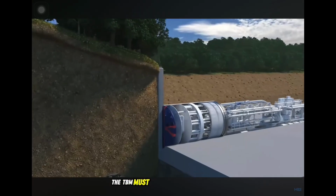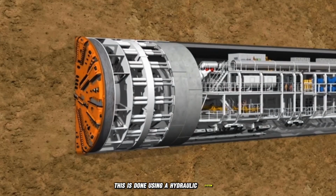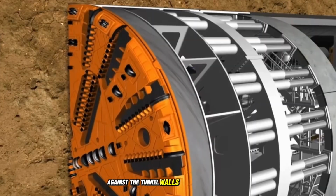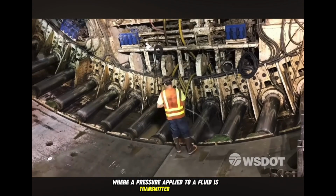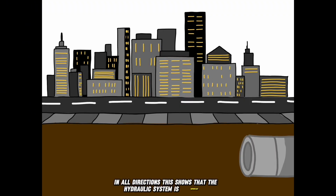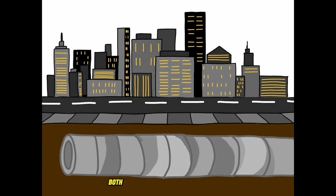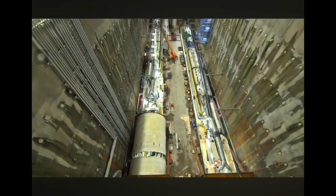The TBM must also move forward while cutting. This is done using a hydraulic system. High-pressure fluid is pumped into thrust cylinders that push the machine forward against the tunnel walls. This uses Pascal's principle, where pressure applied to a fluid is transmitted equally in all directions. This shows that the hydraulic system is important because without forward force, the cutter head would not be able to stay in contact with the rock surface. Both rotation and forward pressure are needed for the TBM to function effectively.